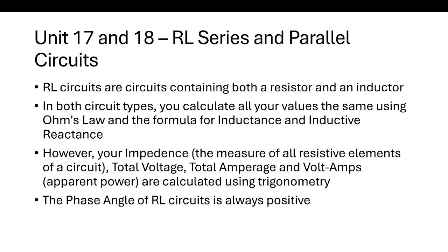In both circuit types, you calculate all your values the same using Ohm's law and the formula for inductance and inductive reactance. So, for voltage, it's I times R. For amps, it's E divided by R. For watts, it's E times I, etc. However, your impedance, your total voltage, your total amperage, and volt amps are calculated using trigonometry depending on how you have it set up. I'll go into it in a minute here. And then the phase angle of RL circuits is always positive.